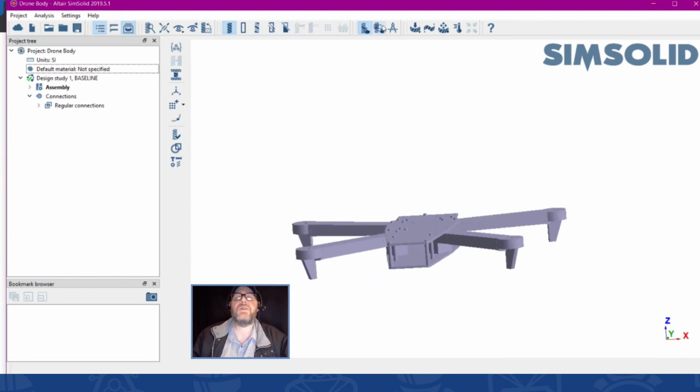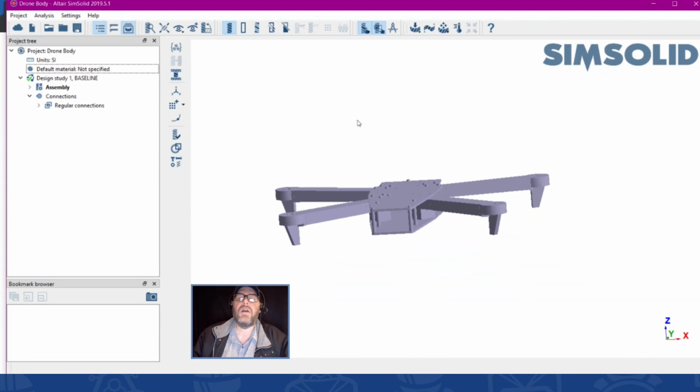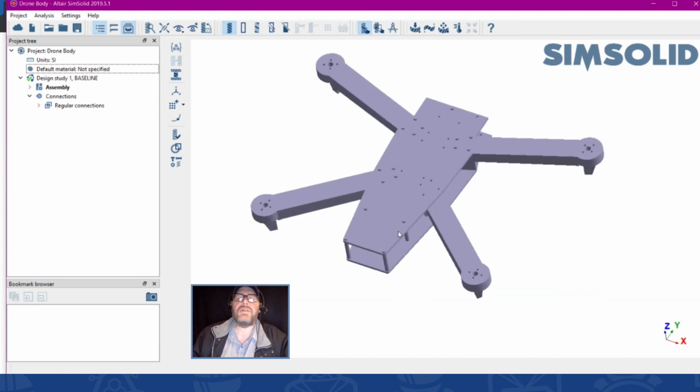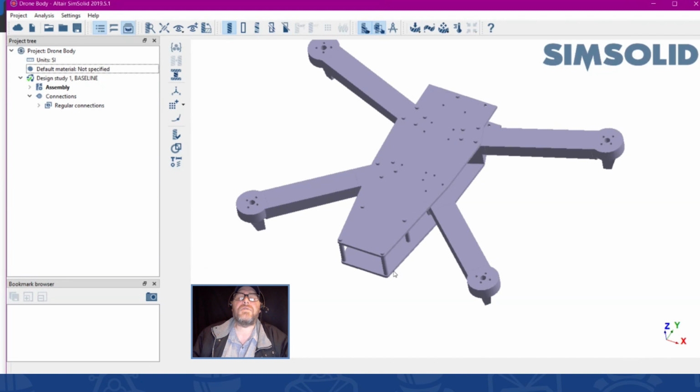A couple of other things. This right here is the box select. When I select that, I can now do a box select and begin to pick things en masse. It will grab anything where I managed to hit the centroid of that particular part. One thing that I do like, let me get it at a better angle here, is that it is aware of which direction you drag from. So if I drag my box from left to right, you see I pretty much grab everything that box is touching.